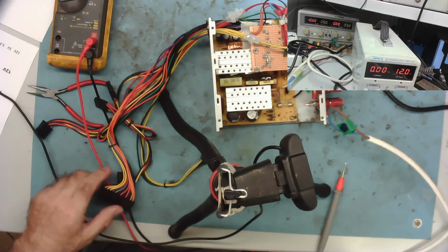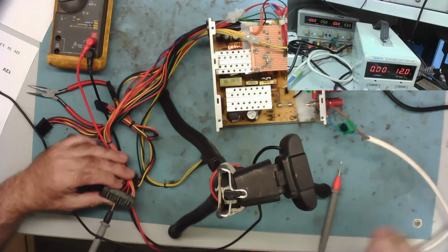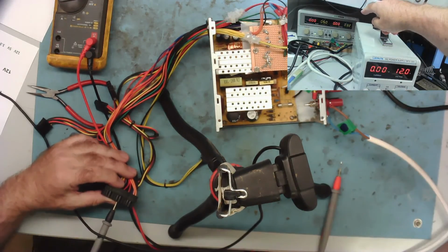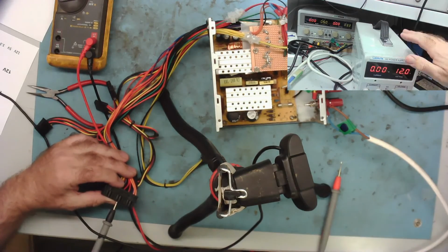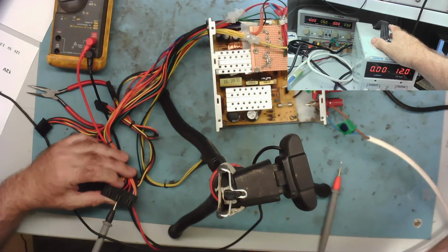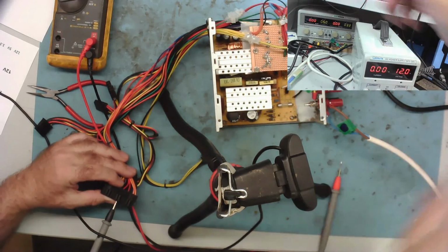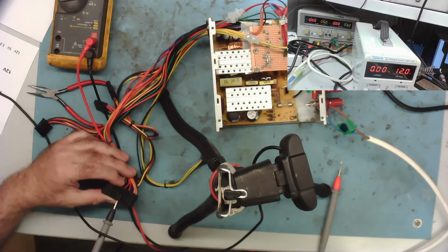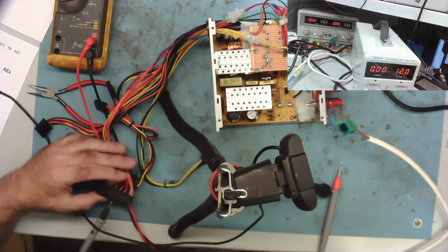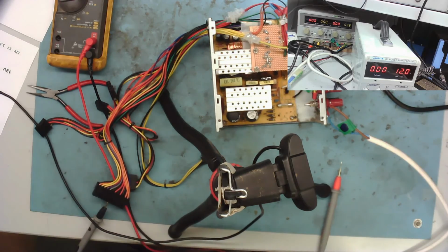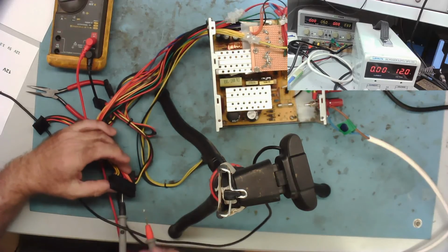It's all set up then. So both the power supplies are on. We've got 5 volts, 3.3 volts and 12. I put the 12 on this one because this is a 5 amp supply. I'm expecting the 12 volts to require the most current. Both the 3.3 and the 5 can supply 3 amps each, so I'm hoping that's going to be enough for just a motherboard. If it's not loading into Windows, it's basically just to power it.